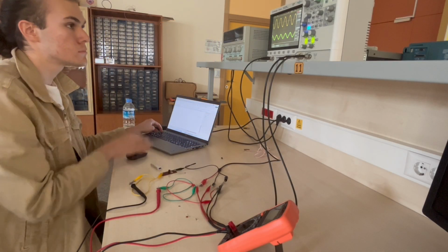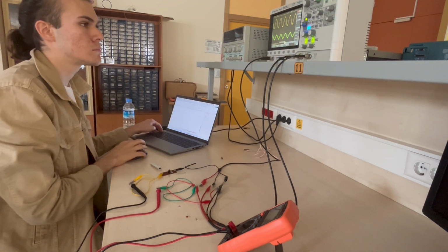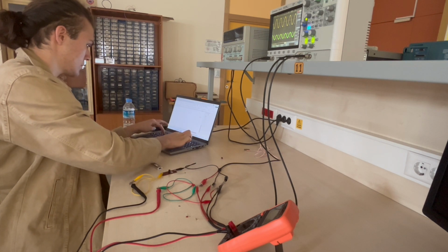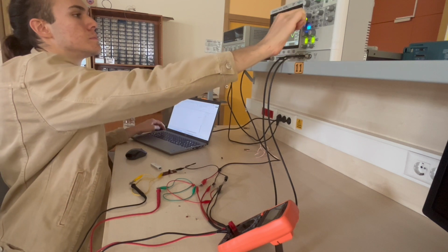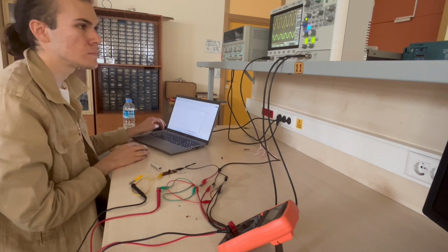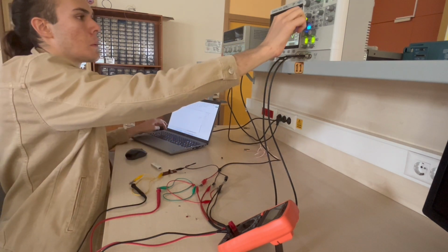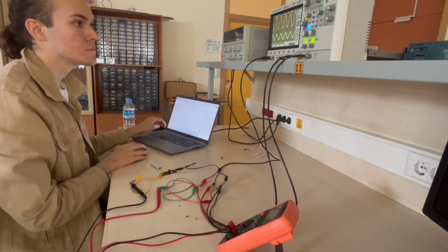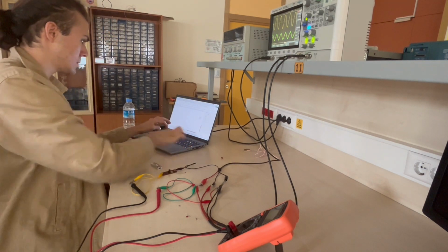This is the first part of my experiment where I apply a particular voltage to the circuit and measure the current using the multimeter and the time delay and phase angle using the oscilloscope. Then I will repeat the same process for different voltages and plot the current versus voltage graph to calculate the impedance. And I will compare impedance and phase angle values with their theoretical values and calculate error percentages for both. In the end, I will repeat the same process for different frequencies.